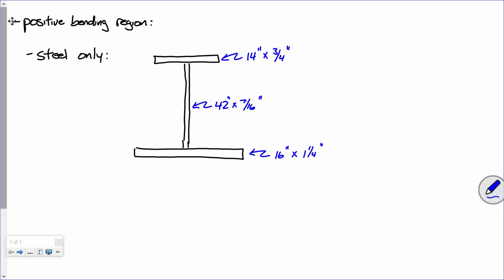So I'm going to create an imaginary point to where we'll start to reference our distances. I'm going to call that the datum, okay? It's a pretty fancy word, but basically when I calculate all of my y distances, I'm going to reference them from the very bottom, okay? And you'll see how we use that here in a second.